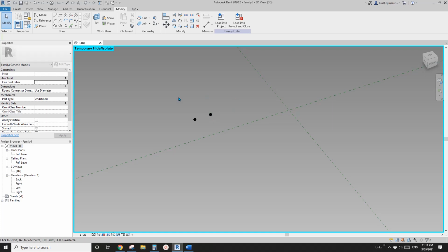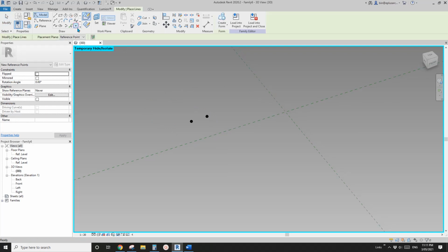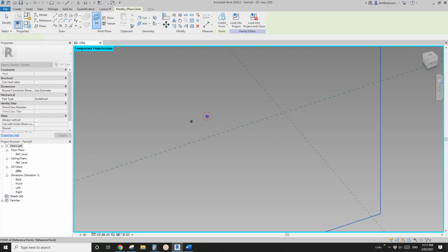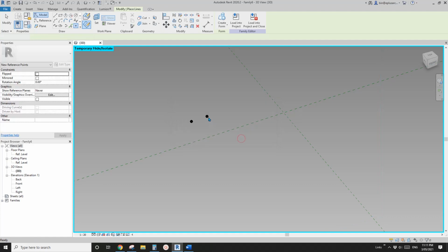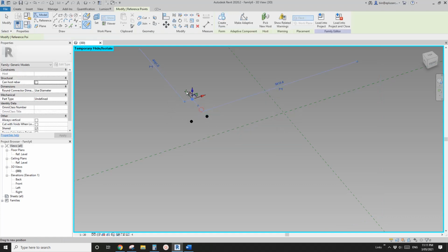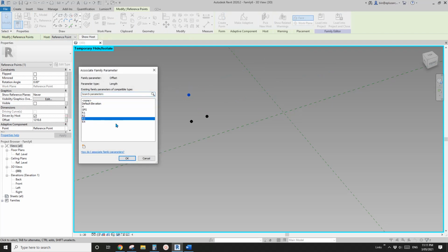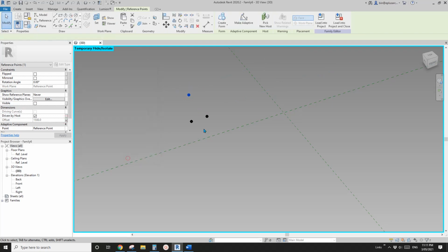What we're going to do is we need to create some profiles first. So we need to place some points. Let's do it. First, place a point, draw a work plane, set work plane, pick the vertical, so this one, and place it on this point. Okay, so now I'm going to drag this that way, and I'll use the R3 parameter.